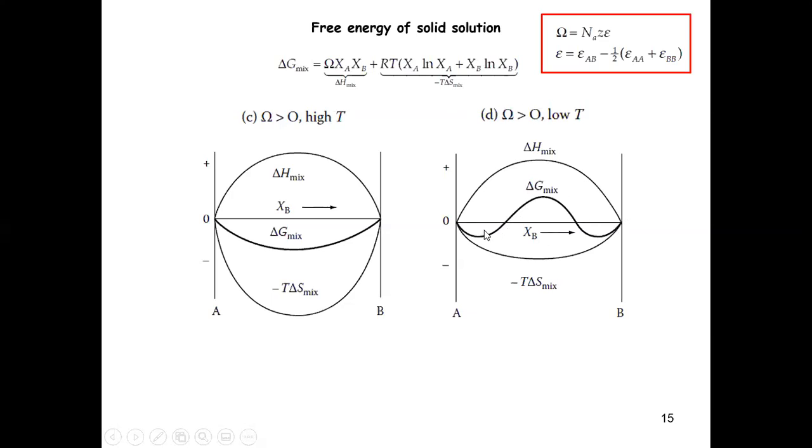Okay, so this means that if you have a very low composition of A in B, meaning you just add a very little bit of A to B, this gives you a fairly small increase of energy. Does that make sense to everyone? If you just add a very small amount, it only gives you a very small cost in energy. Right, because you only have a very small number of AB bonds. The majority of bonds are still AA or BB.